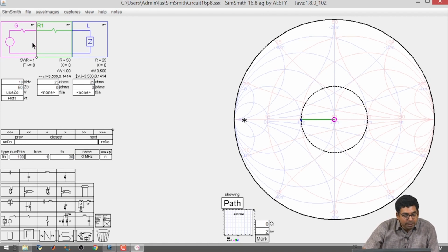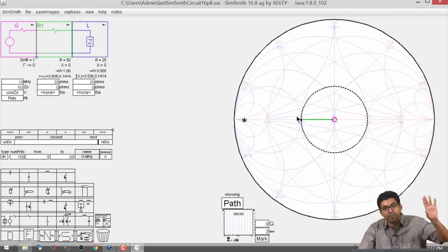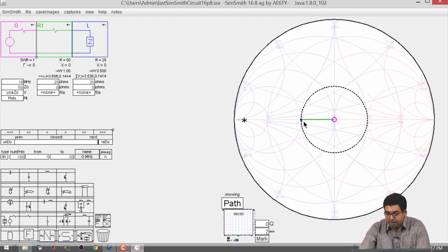And when looked at from the generating side, it looks like it is 50 ohms. So, it is impedance matched, and you will immediately notice that the point in the Smith chart has moved to the center. The blue part is the load, normalized with the 50 ohms, which is where it was originally before we added another resistance.